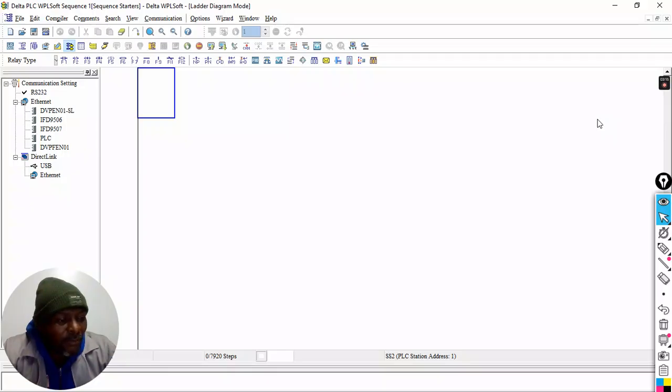Now we have: press the start button, motor. There are 2 motors here. Only after 10 seconds, motor 2 can start, meaning that there's a different start here. It doesn't say after 10 seconds, motor 2 will start, which would make it an automatic move. It says it can start, meaning that someone else will start it. The word can is very crucial there. Understanding the word can is very crucial there.